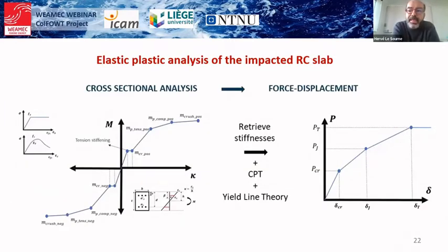Then the elastic plastic force displacement relationships for the reinforced concrete slab have been built by combining the moments found from the cross-sectional analysis with solutions retrieved from classical plate theory and plastic limit analysis for different boundary conditions. The developed subroutine has been compared with detailed nonlinear finite element simulations, and also with experimental tests retrieved from the literature.